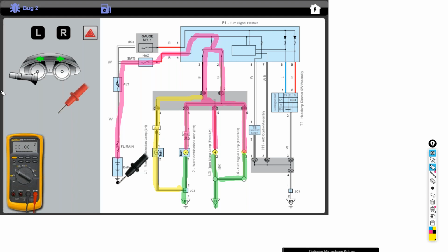A lazy electrician, you'll never see him tear the entire dash out of a car and then pop the trunk and find the short in the trunk. Although I've seen a few techs do that, you don't want to do that. You want to do the easiest thing first. So looking here, they could look up and see DD's connector is under the dash. You have to disassemble a couple of panels to get to it.